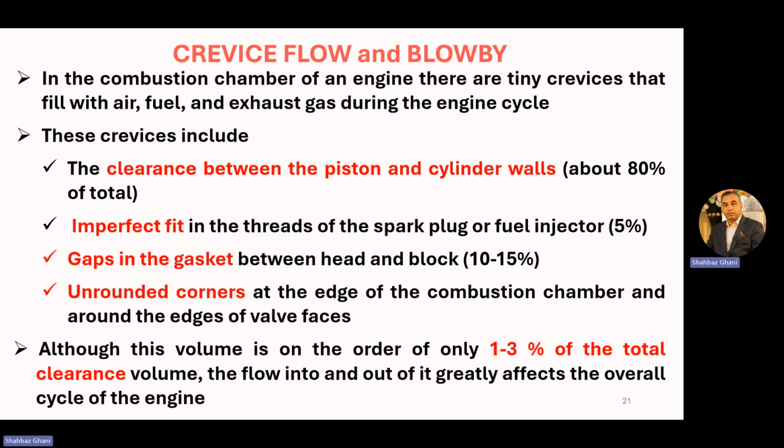Remember, in our first chapter we saw the head on the top and then the engine block. To fasten these two metal surfaces, we must have a gasket. Whenever we couple or fasten two metal portions, we need some gasket in between, and the gaps in the gaskets cause 10 to 15% of the crevice volume.